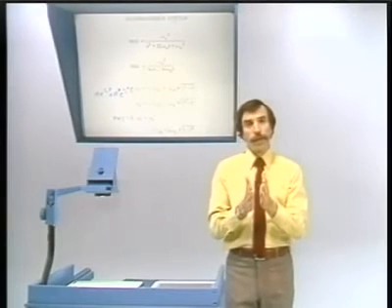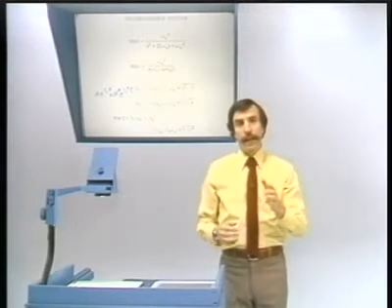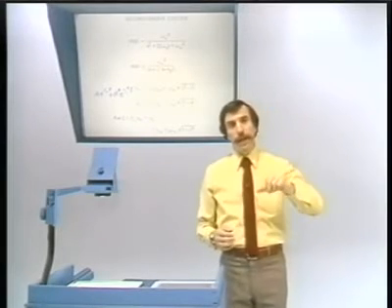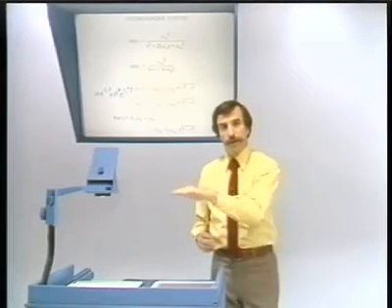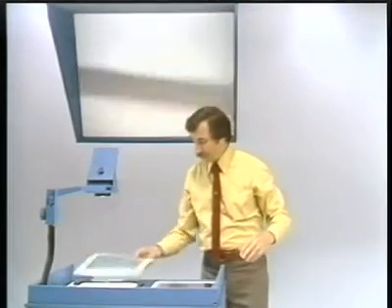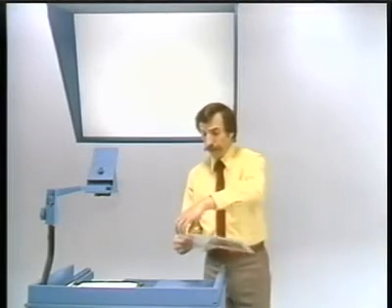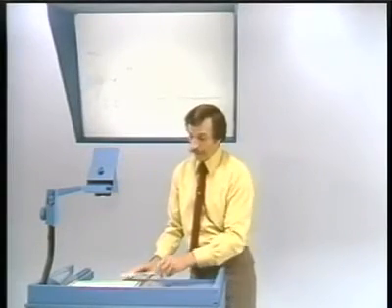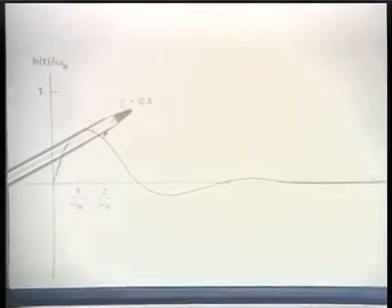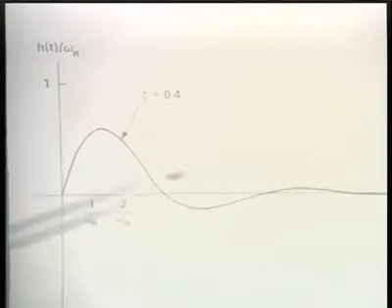In the time domain, the real part of the poles has gotten smaller, and that means the behavior will be more oscillatory and less damped. Just looking at that again, here is what happens in the time domain. First of all, with the parameter zeta equal to 0.4, it oscillates and exponentially dies out.